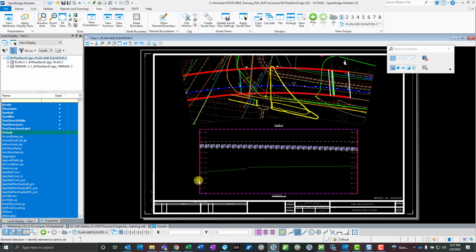And again, I need to go and adjust the profile name boundaries in order to get the overlap distance. Remember, we specified an overlap for our plan view, but it didn't translate into our elevation view here. So we will need to go back and fix that, and we can go ahead and do that now.